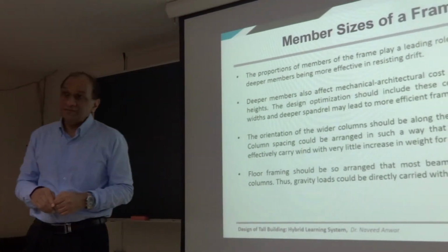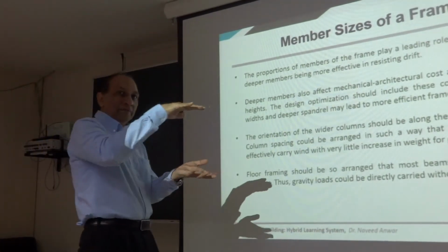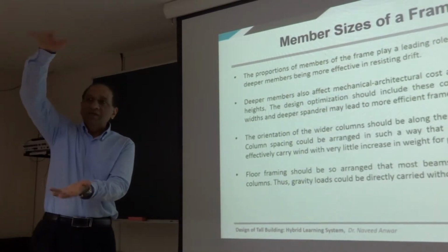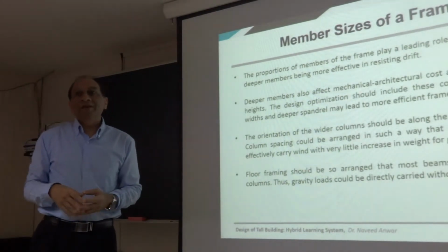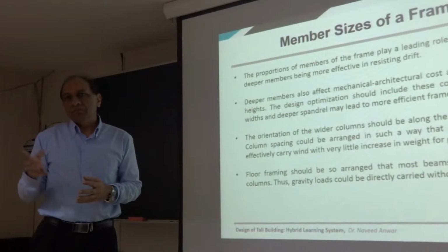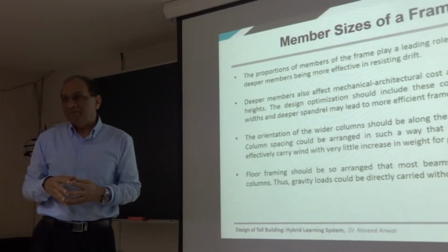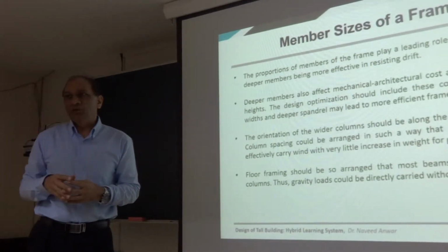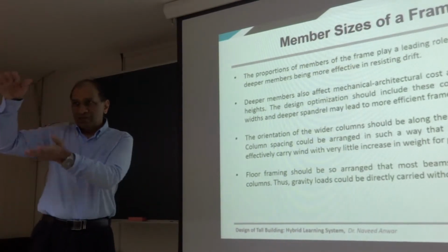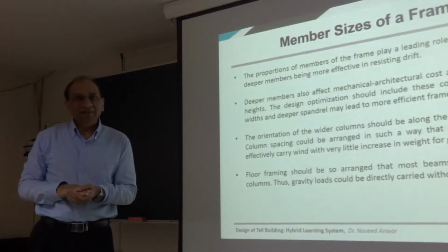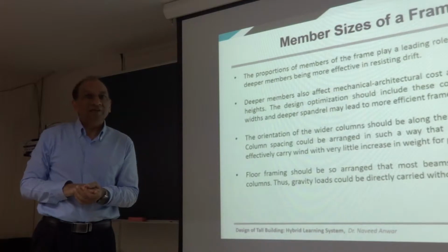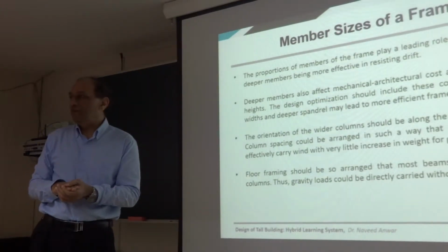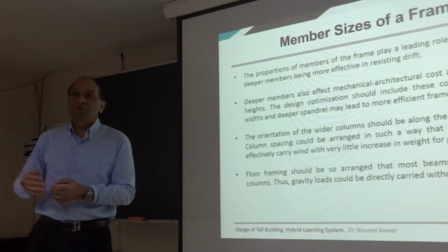That's why flat slabs are there. So if you put a flat slab instead of a beam, let's say for 12 meters, typically the beam will be about 1 meter or 80 centimeters deep. A flat slab will be 250 millimeters. So you take out the beam from there, you reduce about 30-40 centimeters per floor, multiplied by 50. You give them the opportunity to add 4 floors.